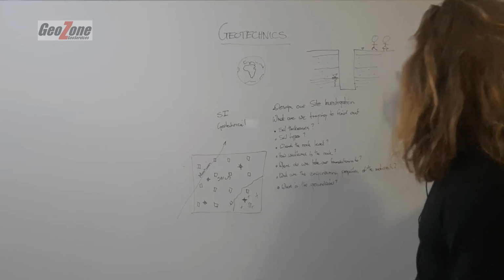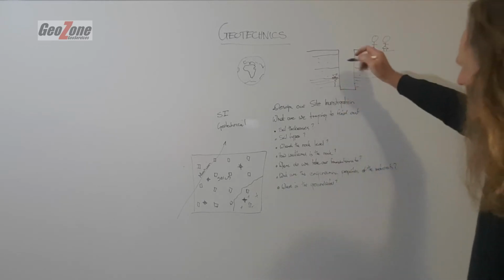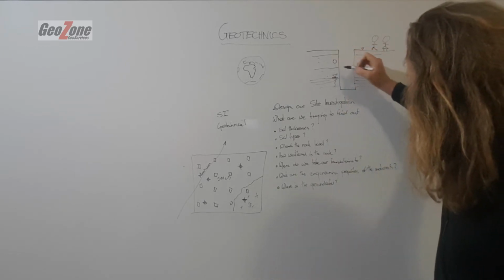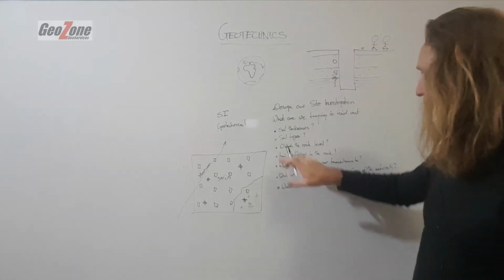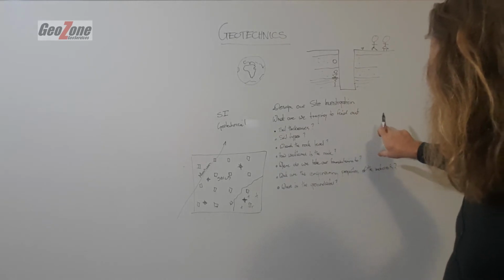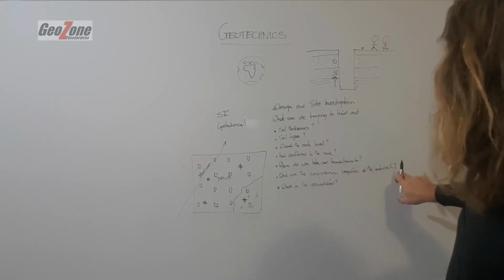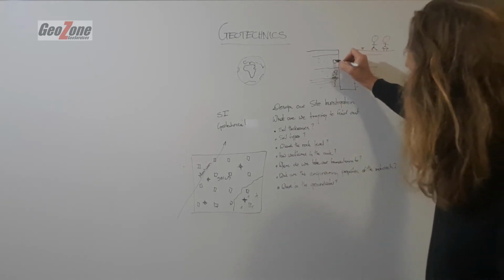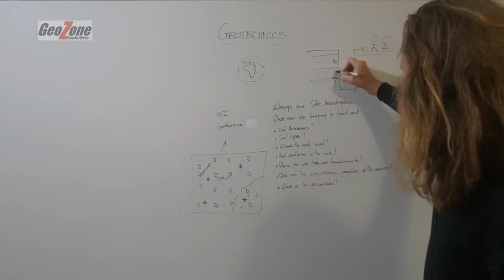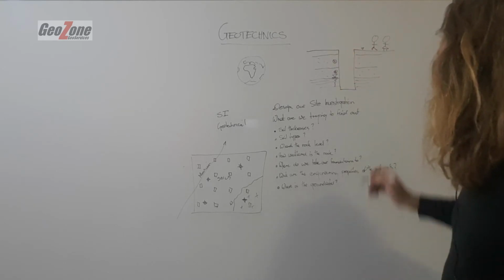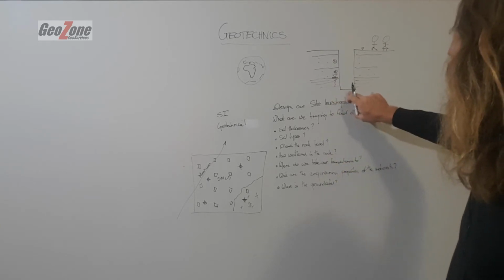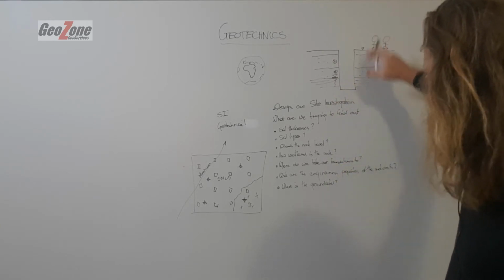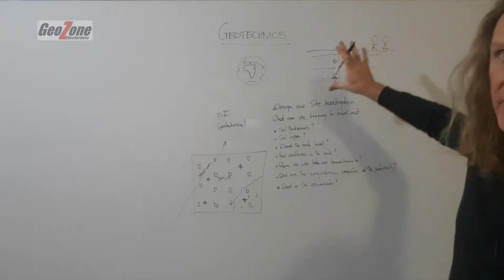With the TLB, we can take samples of the different soil horizons as we go down, put that in the laboratory for testing, which goes back to what are the engineering properties of the materials. So those samples, S here and S here. We know where the water is. We can take our foundations down to this material or this material, depending on how stiff it is, how we think it's going to behave.